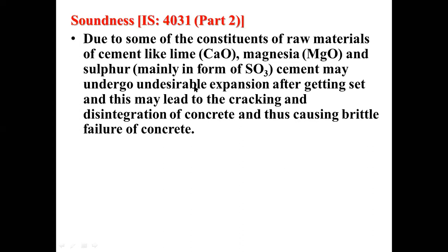Cement may undergo undesirable expansion after setting, and this may lead to cracking. What is going to happen? It is going to expand and cracks are going to develop. That is unwanted expansion. It leads to cracking and disintegration of the concrete, thus causing brittle failure of the concrete. That's why we conduct the soundness test.